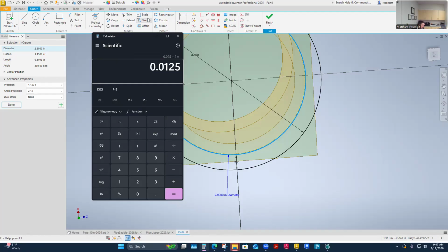I could even go on the rack out, if we're building our own equipment, I could go look at the 3-inch pipe and be like, does it have a big old ugly seam inside of it? And if it does, I might be like, if I just use schedule 40, you'll have a sloppier weld fit, but you'll definitely probably have to do less grinding on the inside of one potentially. So these are things you have to think about, but you have to know your materials as well.